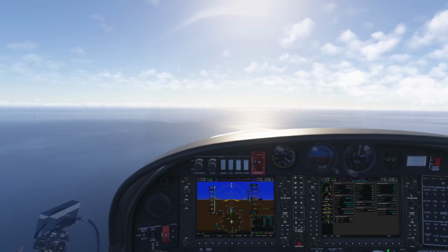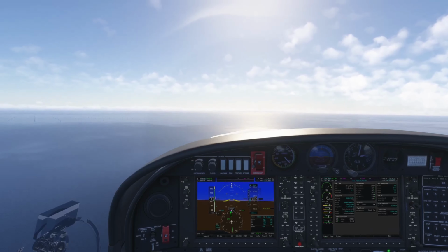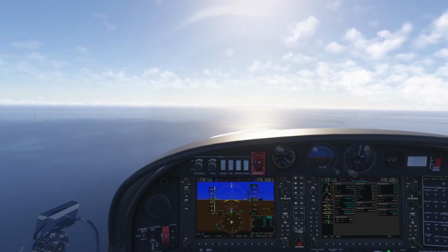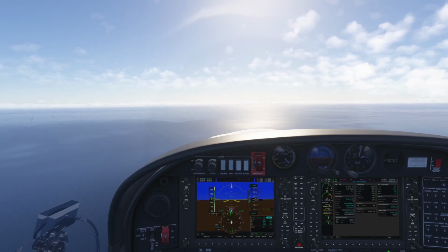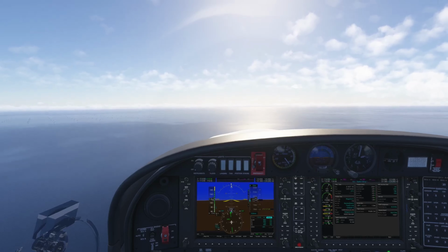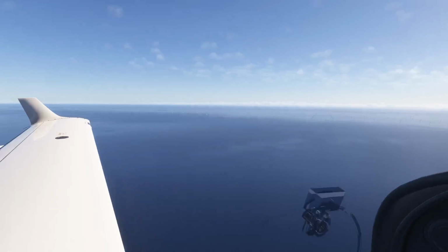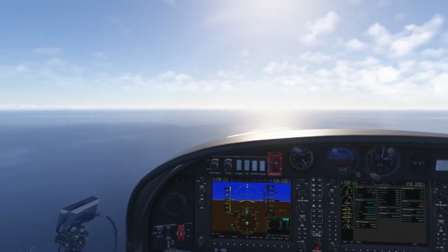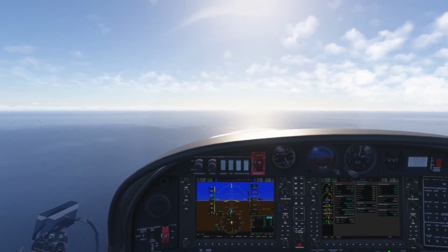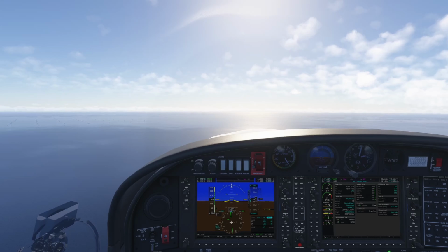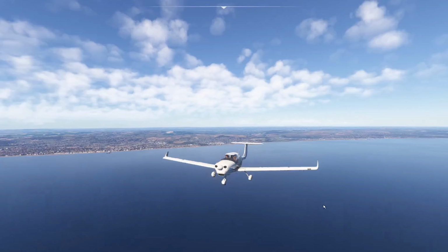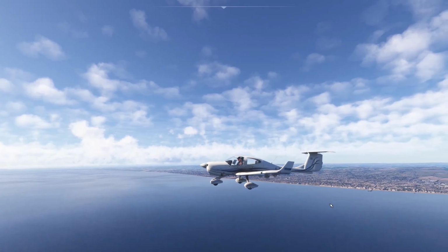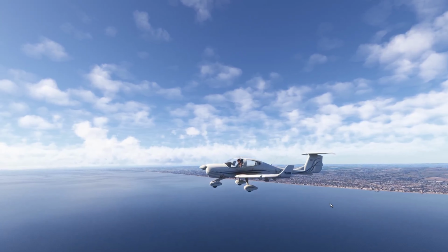5 knots above our speed, 5 knots below our speed, we're going to slowly reduce to 65% load, which should give us 110 knots. And we're just going to get ourselves trimmed down. And we can use 110 for the navigation. And as you can see, we've got the aircraft trimmed. So, that is how you depart in the DA40, your startup, taxi and takeoff.